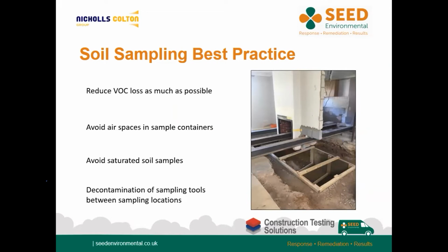The first is to submit an intact core sealed to prevent loss of VOCs, and the second is that a small portion of the material is taken with a coring device and immediately placed in water or a preservative, which is subsequently sealed in a vial for submission to the laboratory. We at SEED adopt the first option, with all headspace being removed from the sample container. It should be noted, testing for non-volatile contaminants, for example, metals and PAHs, do not require such a specific practice.